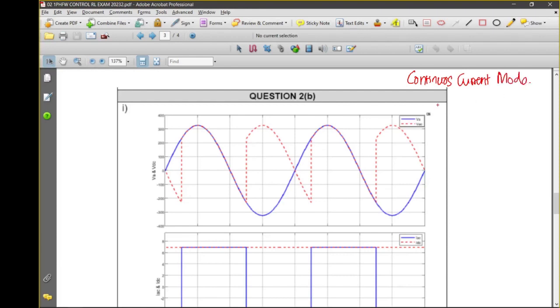So in this case, if you refer to the notes, then we have this output voltage because at the beginning, the current flowing in the circuit forces thyristor 2 and thyristor 3 to turn on, and therefore you have this output voltage, a copy or the negative of that voltage here.